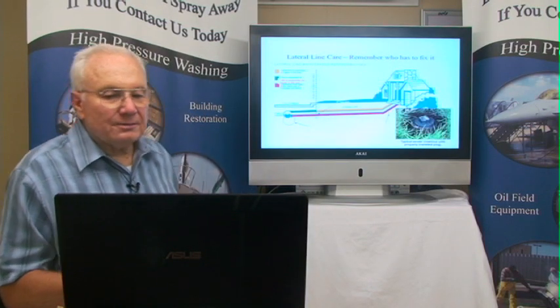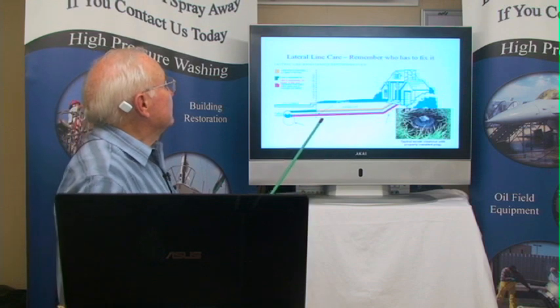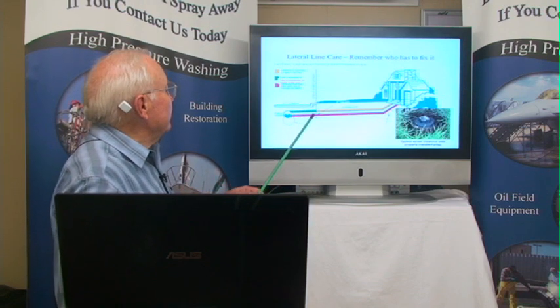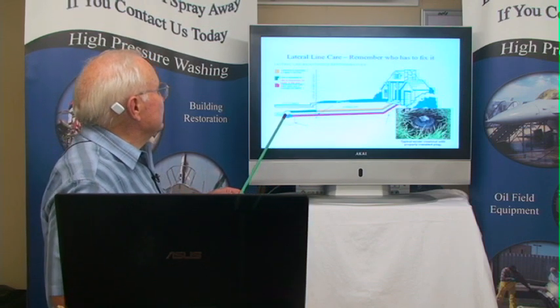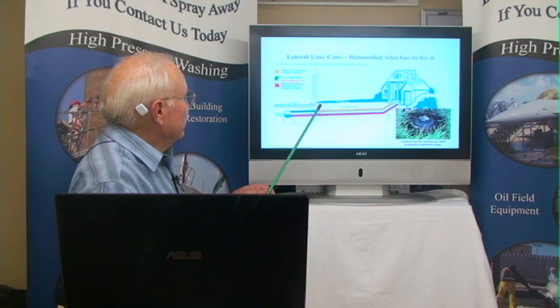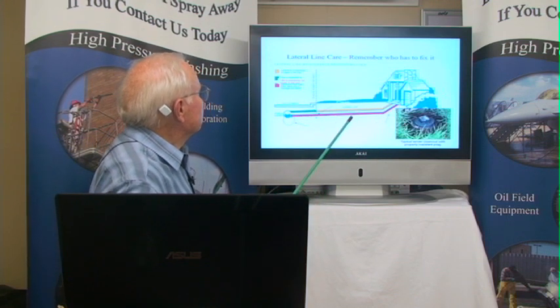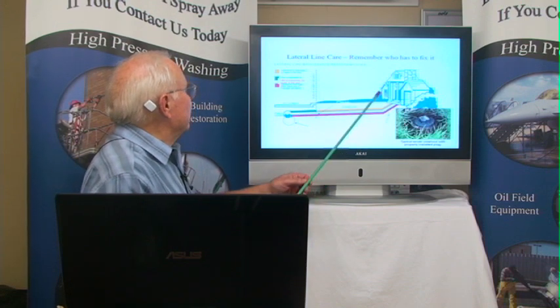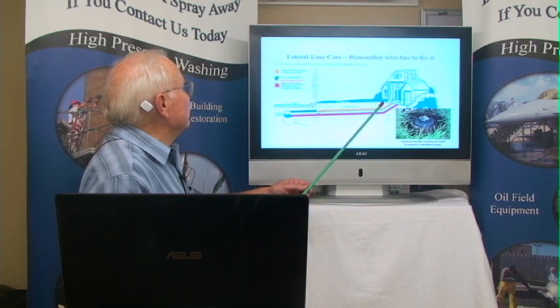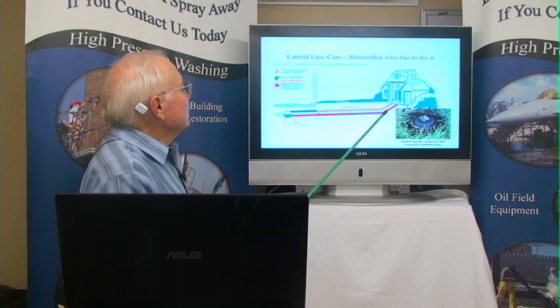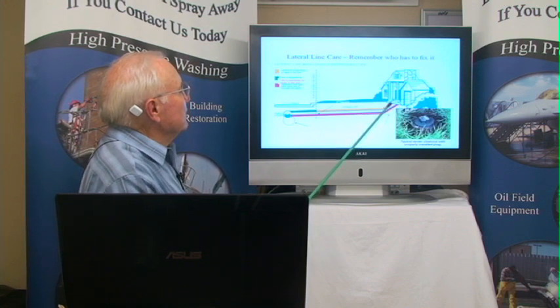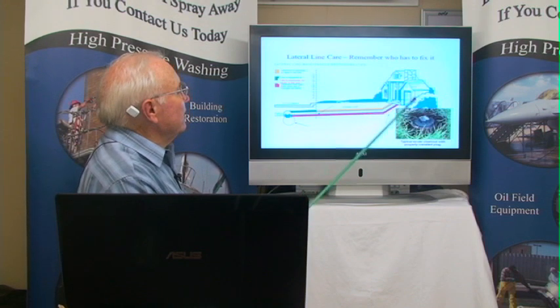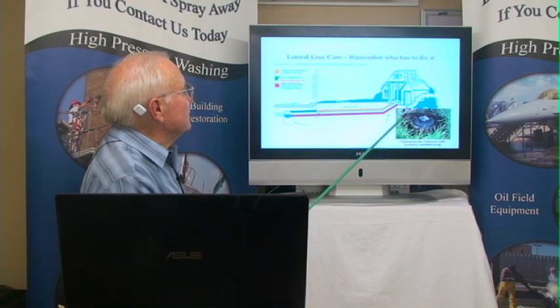Lateral lines. Okay, here's the street right here. On out here is the public sewer system. Here's private property. So your clean-out ports are going to be in this area here. So the clean-out port, and there's an example one, is going to be on the outside of almost those facilities.